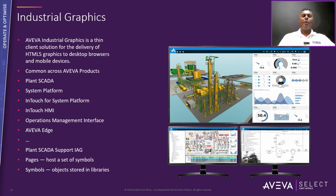Industrial Graphics offers the following benefits: HTML5 visualization that can work across desktop and on mobile with the Android or iOS app. You only need to learn one tool and technology to create the visualization from edge to desktop to cloud. Graphics can be shared with minimal modification to work on any product utilizing industrial graphics. Plant SCADA supports two types of industrial graphics. The first being pages, which is used to host a set of symbols, and symbols, these are industrial graphic objects that are stored within libraries.